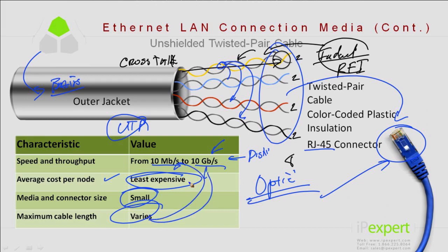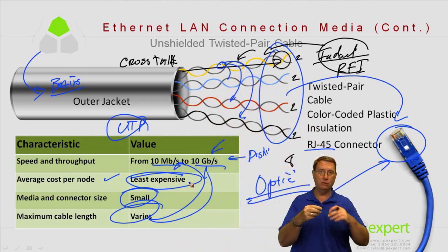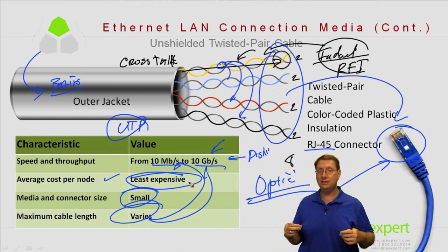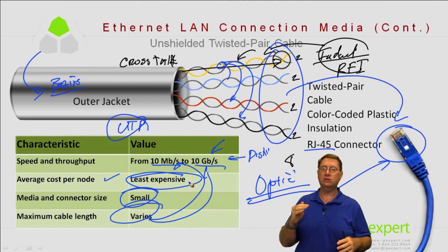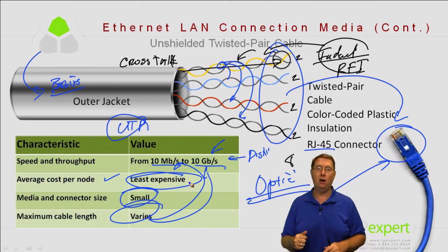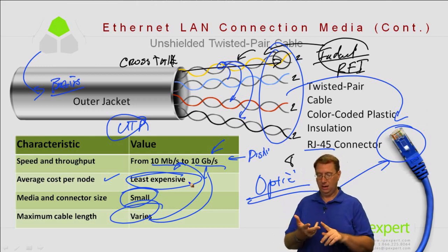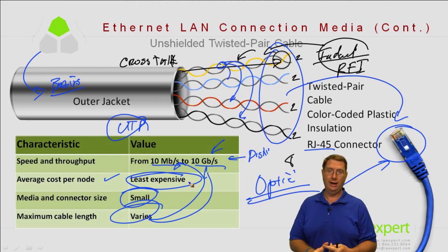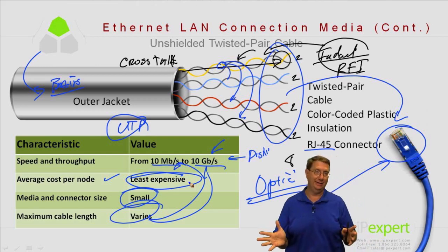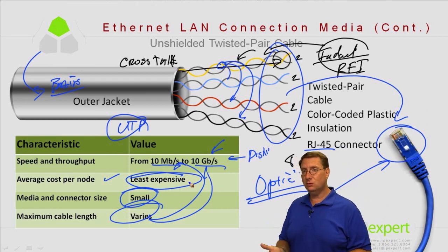Also bear in mind that inside of this individual cable, we have four pairs of wires that are twisted, and each pair is typically going to be a solid color and what's referred to as a striped color. So I'm going to have blue, blue-white; brown, brown-white; orange and orange-white; and then green and green-white, adding up to 8 conductors. Now, depending on how I want to do my terminations, that's going to determine how I'm going to utilize those individual cables.